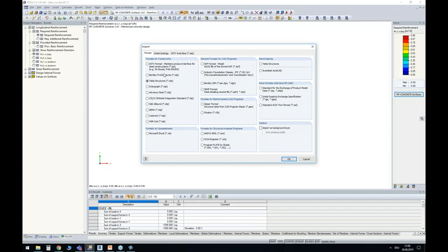It contains information about materials, sections, hinges, and eccentricities. You can exchange the different member types that we have, truss, tension, and so on. Nodal supports can be saved in these files, member elastic beddings, sets of members, even loads and combinations and results. So this file format, even though it's a little bit old, is still very strong. Whenever you have an option, so if both programs that you're using enable you to export into the DSTV format, you should give it a try.